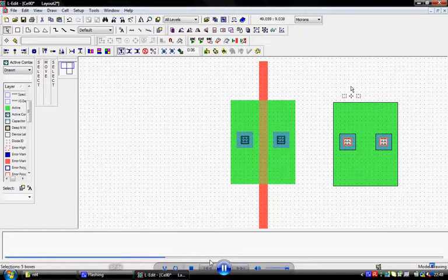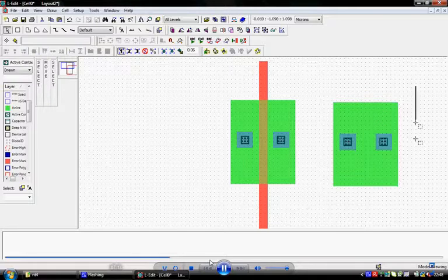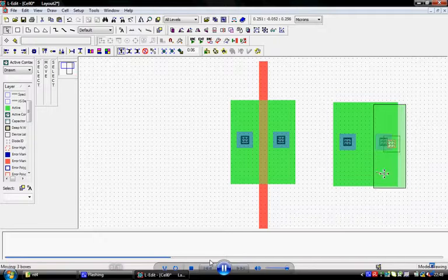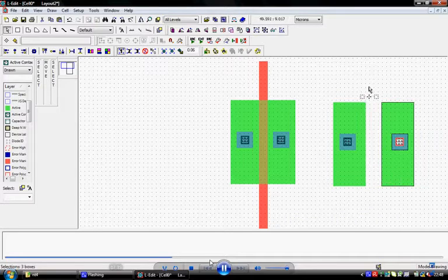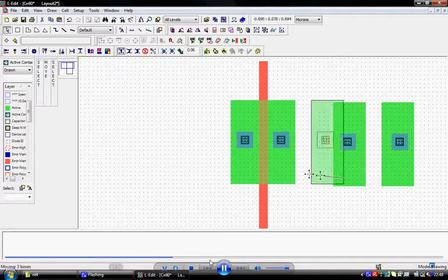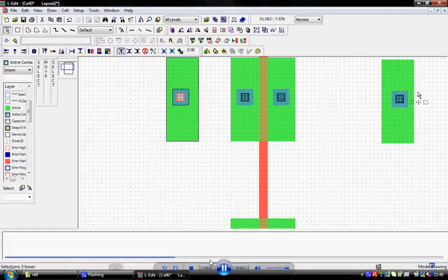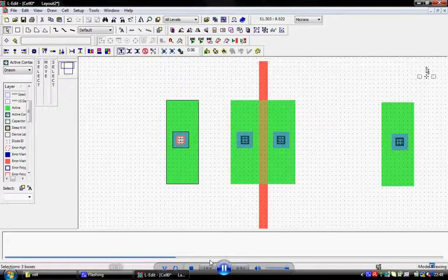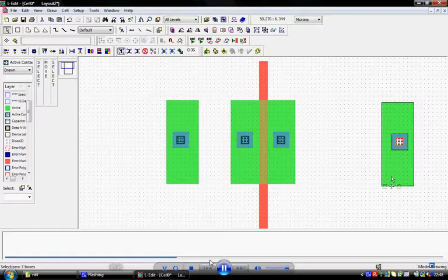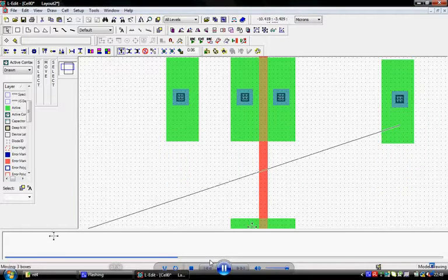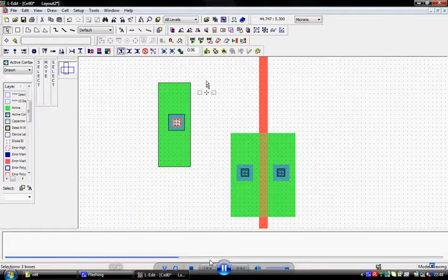then paste it on the side edge, place it on the side edge, then using cut selected objects across vertical axis, using this place it in the center and click it. Once you click it, the layers will be divided vertically. Now select half of it and separate it. Select this particular object, place it next to one MOSFET diffusion, and select the other layer and place it on the other side. Place it below.